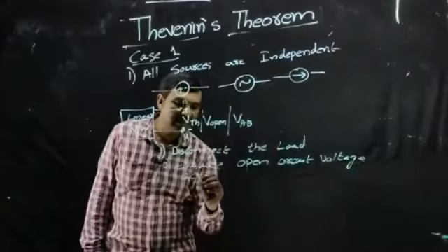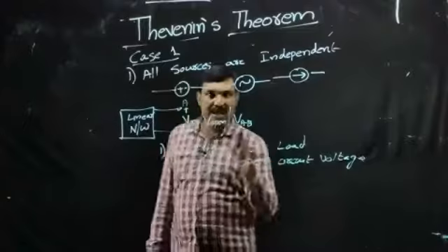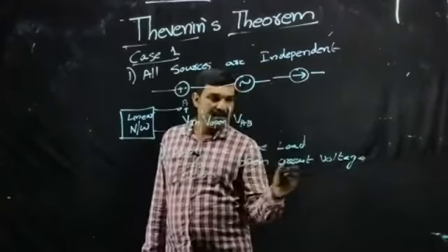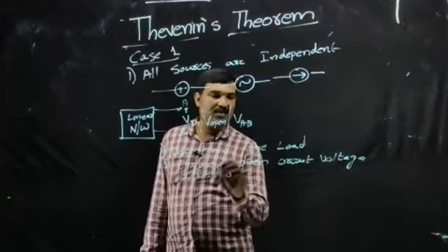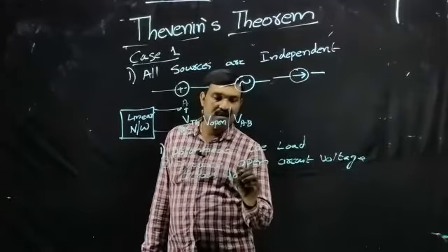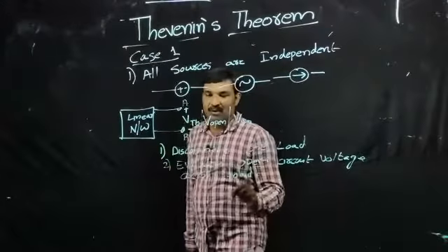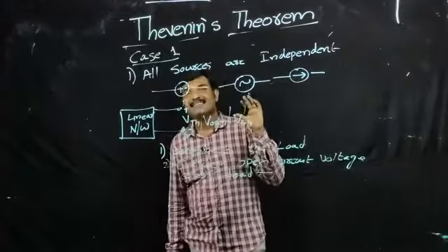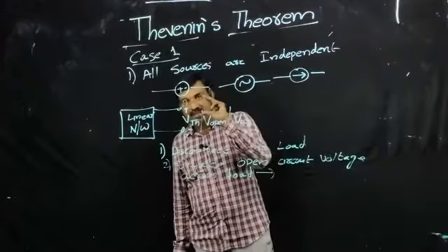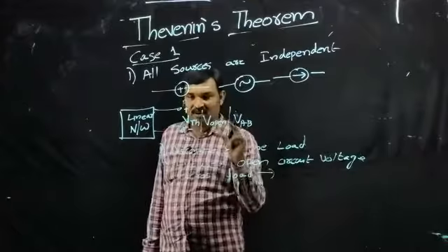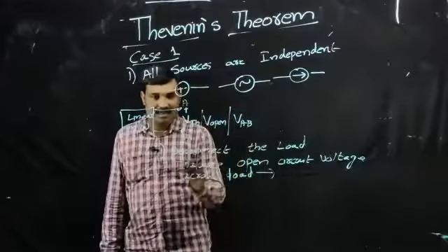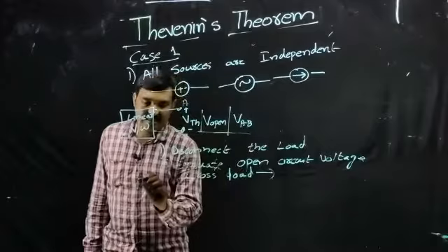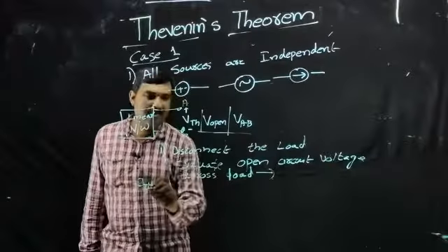So first you disconnect the load and determine the value of voltage across that open circuit. We just disconnect the load and measure the voltage across that open circuit load. Then we have to determine RTH, right? This is the step for determining VTH.